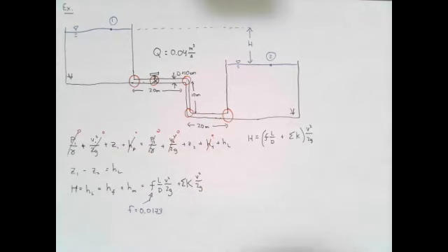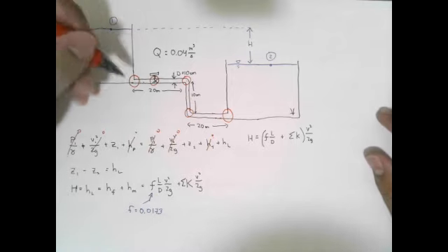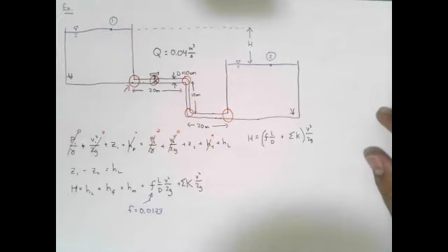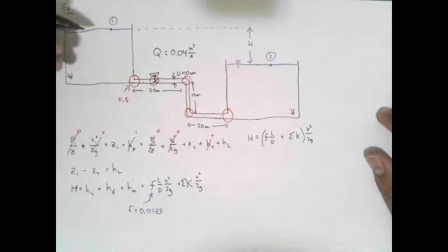You'll notice that identifying these components is the hardest part of the job. Perhaps not in this class, because for test purposes, I have to give you those coefficients. But perhaps when we're dealing with an actual system, identifying them would be pretty much the hardest part. So let's say that you identified them and you used your investigative powers of Google to find the minor loss coefficients for all these fittings.